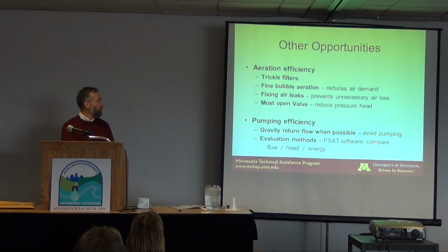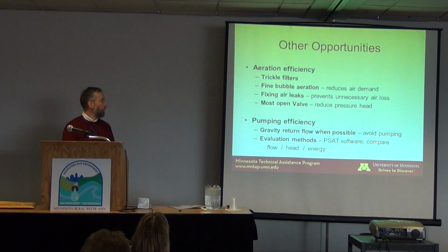Yes, so just on the pumping efficiency, there are some ways to evaluate pump efficiencies. Basically, looking at the flow that's provided, divided by the head, divided by energy, gives you essentially a pumping efficiency measure. And if you look at the different pumps and look at this pumping benchmark, you can get a sense of which pumps may be less efficient in your plant, and that may be worth taking a more serious look. Next.